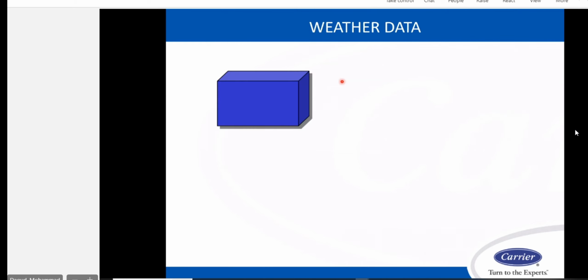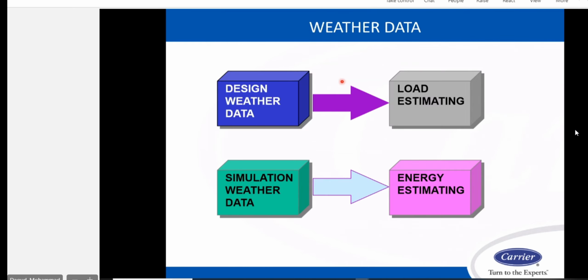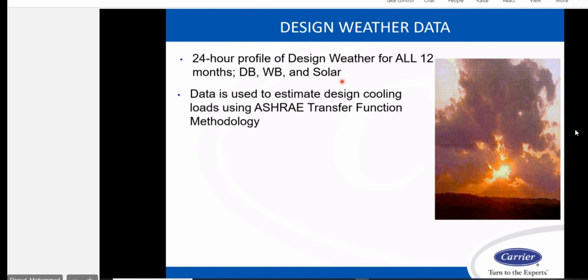The weather data. We can have both design weather data, which we need for load estimation, like for 24 hours, or we can have it for the whole year for simulation data for the energy estimation.